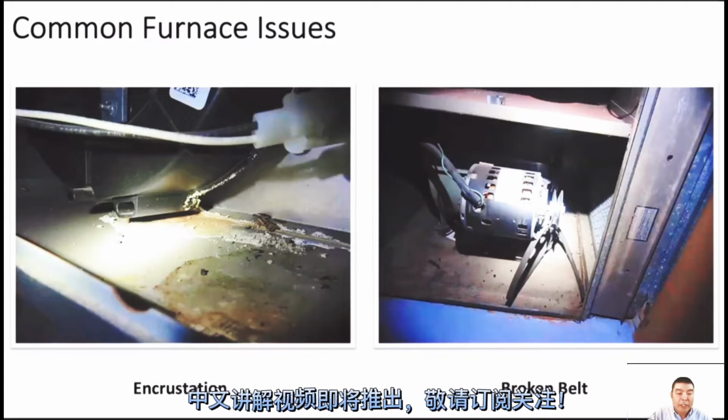If it's running a long time, you can even smell it from outside at the exhaust terminal. You can smell a very bad smell there. High efficiency furnaces are notorious for leaks around the inducer motor. While there may be a leak during the inspection, maybe not. Sometimes if the furnace is not running, you only see steam, so you cannot see the real water leak there.